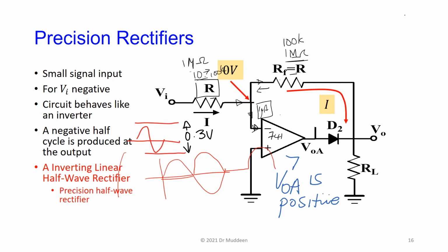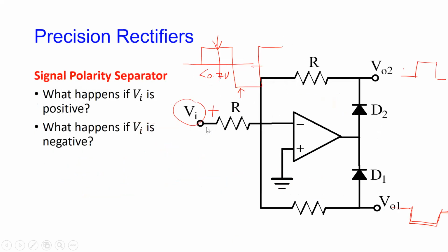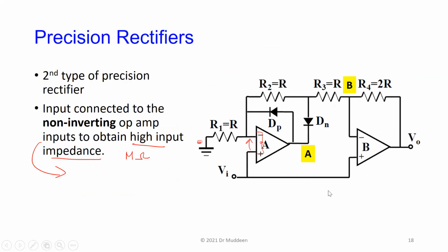So you're not getting that much input impedance, but this version now, because inherently, because of the circuit design of most op-amps, even a 741 op-amp, the non-inverting input impedance is already bigger than 1 megohm, right?